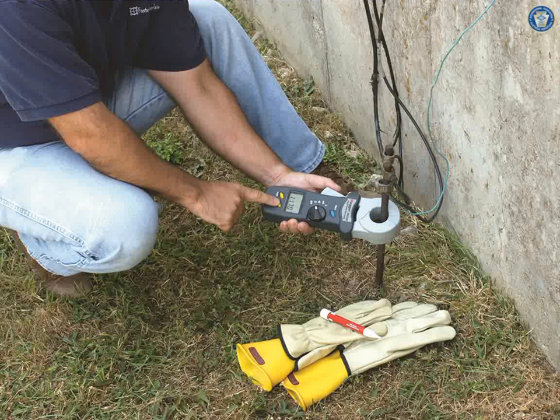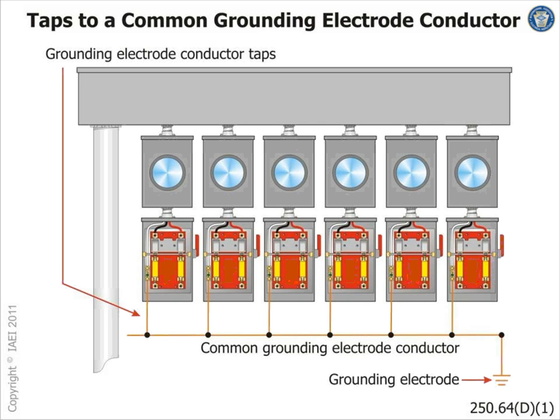This is where you measure the ground, the impedance of the ground. The NEC code book says if it's more than 25, you have to supplement it if it's a rod or ground. Here's where you can see how the services are, multiple services here. You can see the neutrals coming to every service and bonded to the grounding electrode system at the service too.